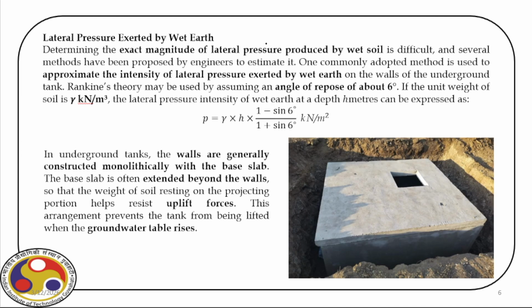The first thing we have to consider is the lateral pressure due to the soil. As you can see here, there is no soil here, and later on the soil is filled, and the moment it is filled, the wall of the storage tank experiences a soil pressure.